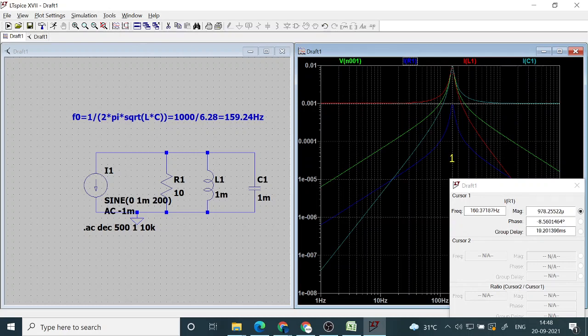If I match exactly with the peak, you can see the frequency. Here I got 160, while our calculation is 159.4. Some measuring error will be there, so let us ignore it. We are getting the peak at the correct frequency which we expected. Maybe I have not put it exactly at the peak. It's very difficult to get exactly, otherwise you have to magnify and try.